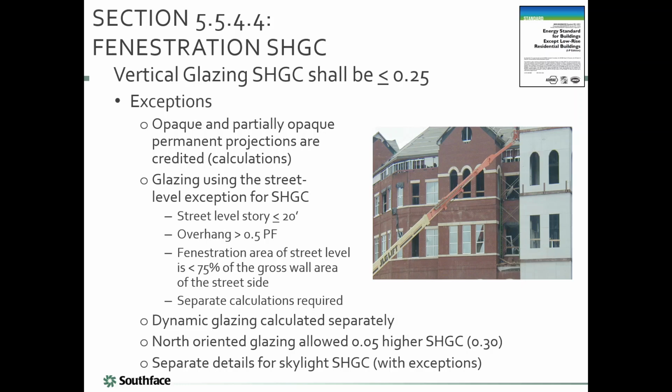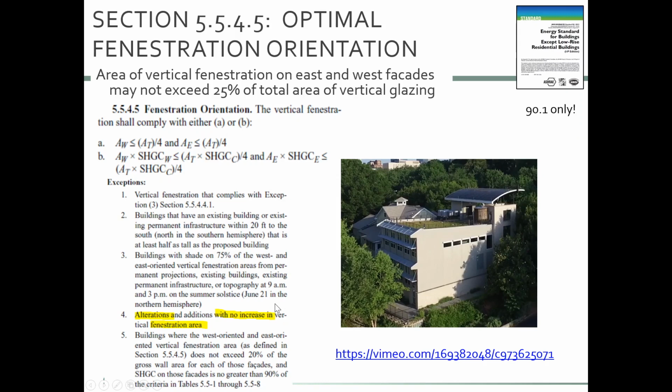So this is our building. You can see there's a lot of good glass on the south. You can't see the north facade over here. It's got a lot of light, a lot of windows as well. North windows, you can get reflected daylight in about 15 feet. South windows with light shelves and shading devices, you can even get natural daylight kicked 30, 40 feet into the space. And then there are no windows on the west facade.